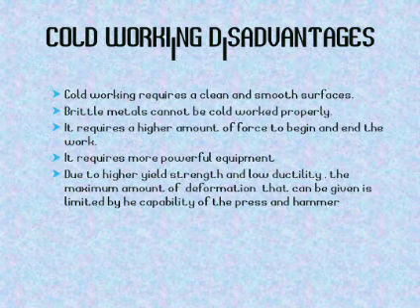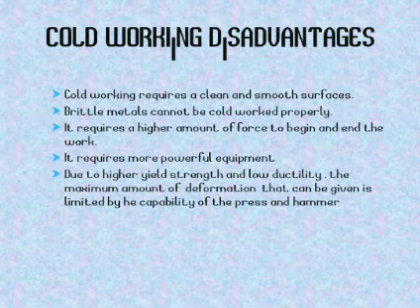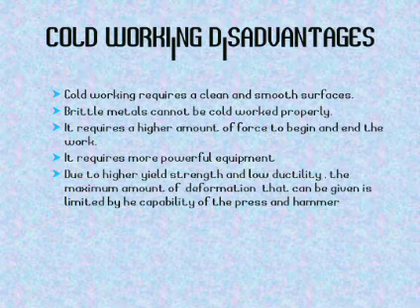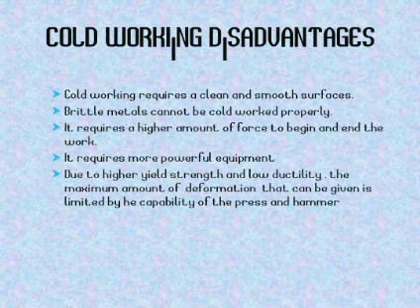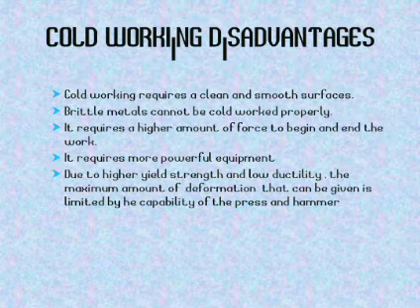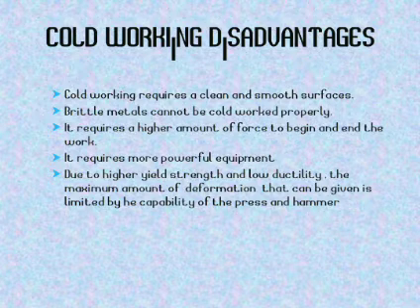We also have the cold working disadvantages. Cold working requires clean and smooth surfaces. Brittle metals cannot be cold worked properly, and it requires a higher amount of force to begin and end the work. It also requires more powerful equipment, and due to higher yield strength and low ductility, the maximum amount of deformation that can be given is limited by the capability of the press and hammer.